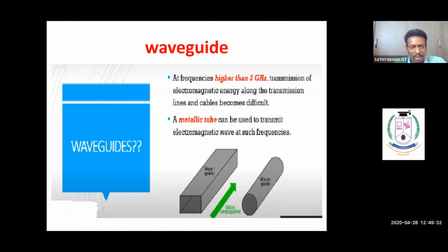Okay, so coming to this, what are waveguides? As I said, a waveguide is a rectangular metallic tube. In a parallel plate waveguide, you can have TE mode, you can have TM mode, and you can have TEM mode. But when you close the two sides, when it becomes a closed structure, then for waveguides you have only two modes that exist. That is, you'll be able to launch or send signal only in two configurations: TE mode or TM mode. And we can make waveguides in two different shapes, either a rectangular tube or a circular tube.